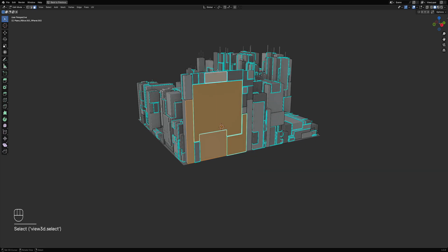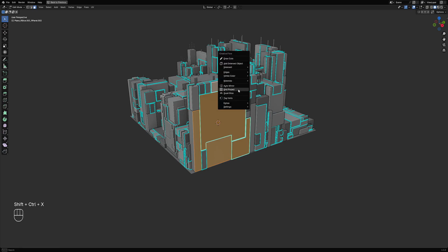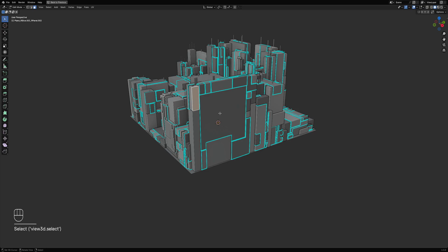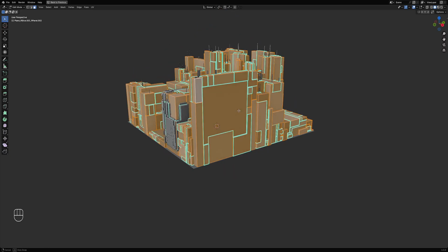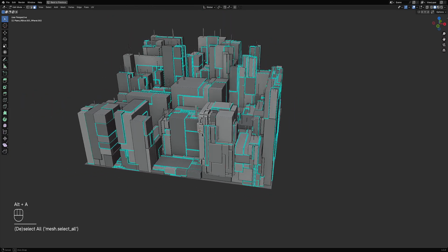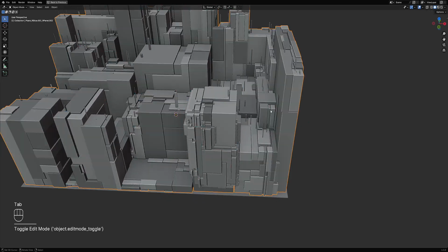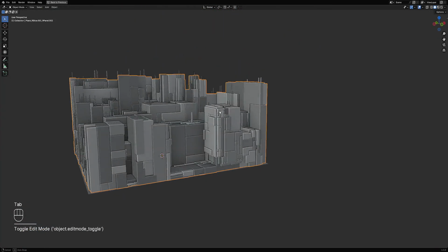But these are. So it's designed to work like that. And also grid project, they're designed to work on faces that are on the same plane. So don't use it on this kind of selection. It will probably freeze Blender. So that's how you add the additional detail.